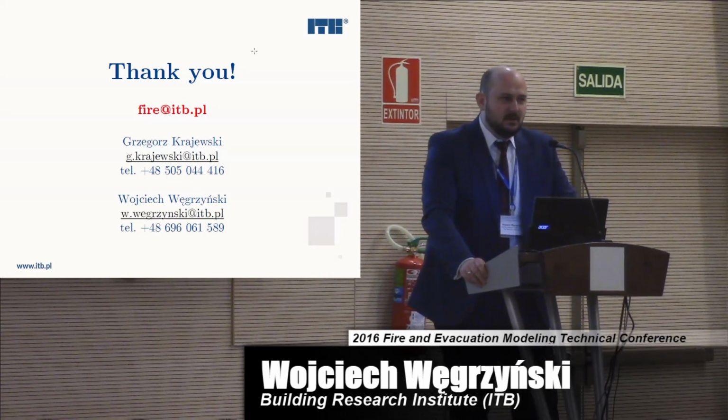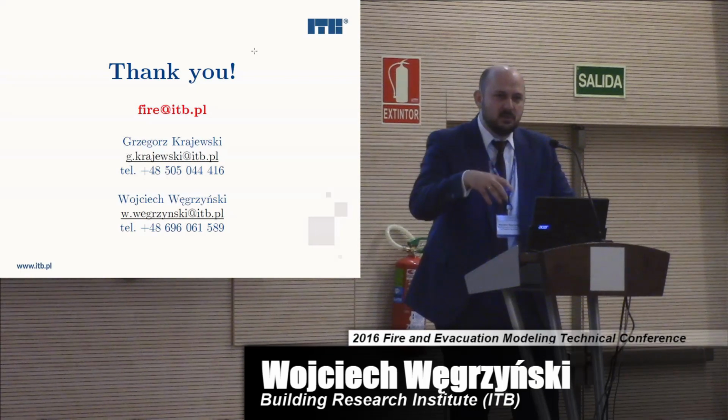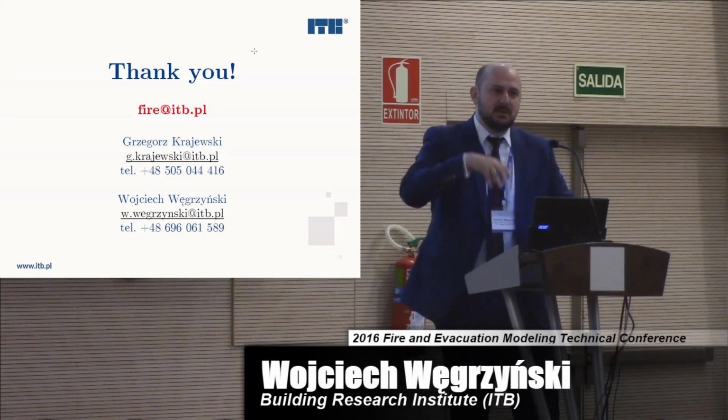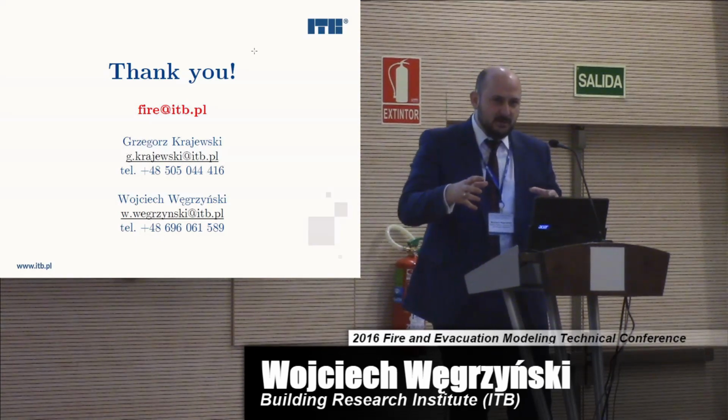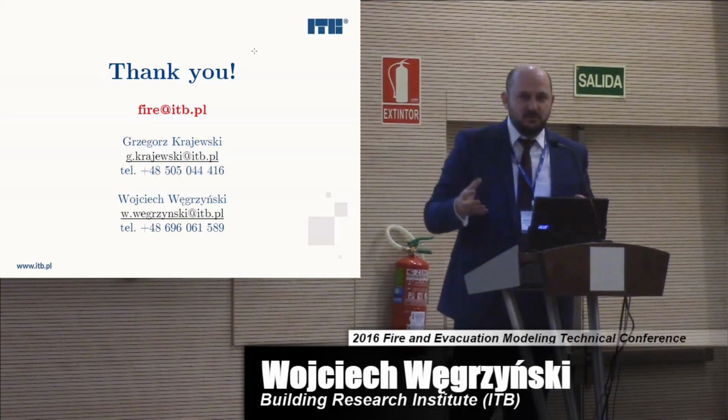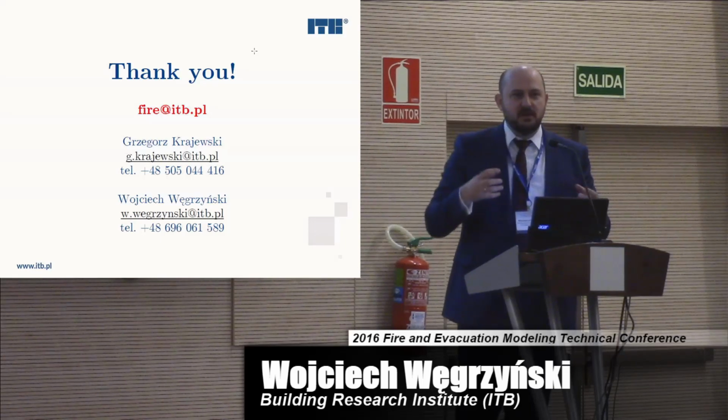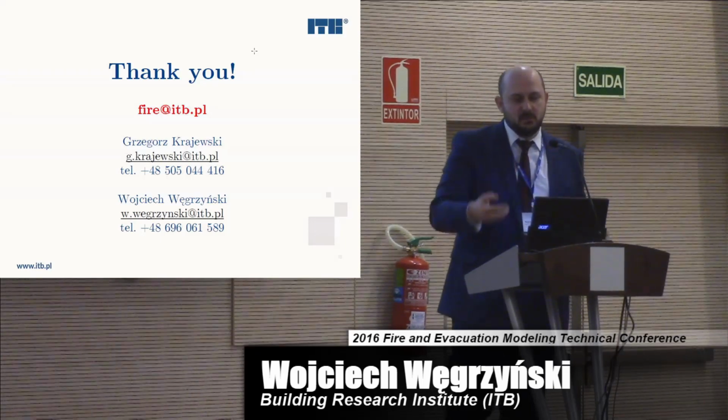Okay, we cheat and we run an ANSYS simulation for wind, and once we find the worst case scenario, we just rerun the same simulation, but including fire and in a transient mode. So it's the same model, but we don't turn on the interior of the building until we need it. So first we find what's the worst case scenario, and then we implement that.